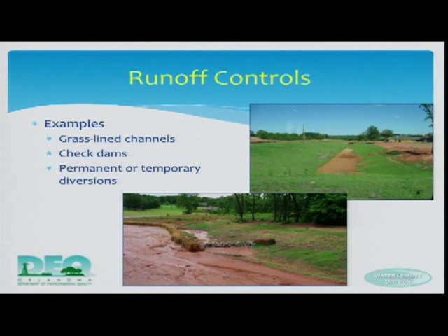And so you can help yourself out a lot if you're going in to develop a site that's an old farm or something like that. It may have a bunch of terraces on it already. Then you can just leave them there until you're ready to take them out. So things like rock check dams down in the lower middle there, permanent or temporary diversions of the water, things to slow that water down and knock the sediment out. You can see there in the upper right, that's what happened in that grassline channel. The water hit there and it slowed down enough that it dropped out all the heavy stuff. Probably there was some red water flowed out of there, but it wasn't carrying a whole lot of sediment.